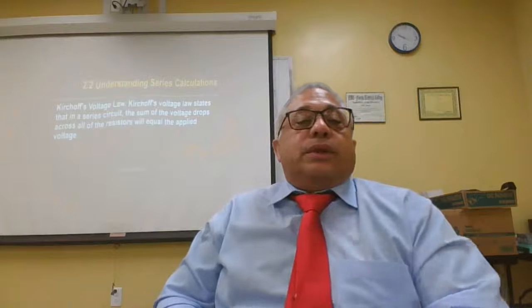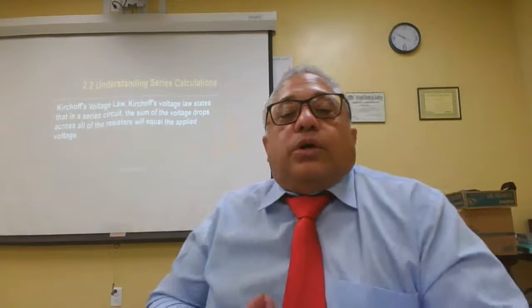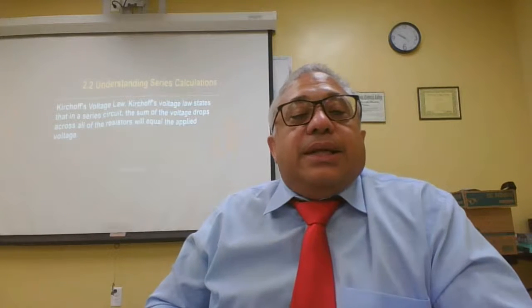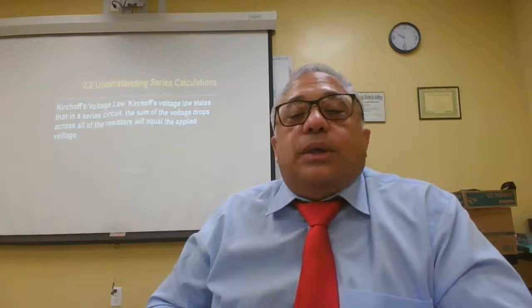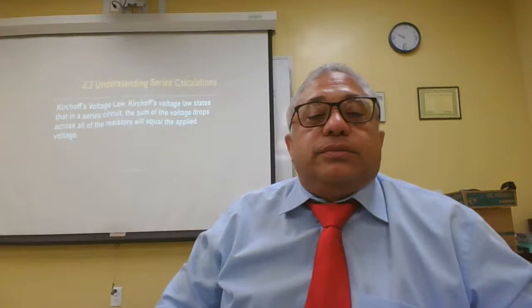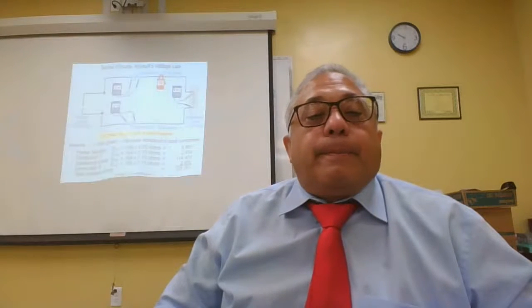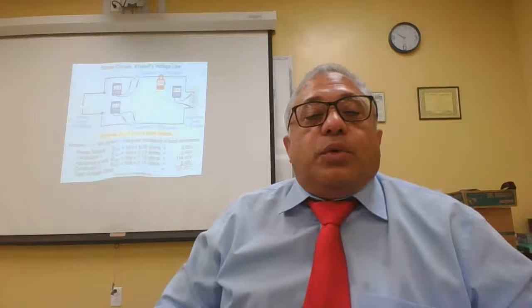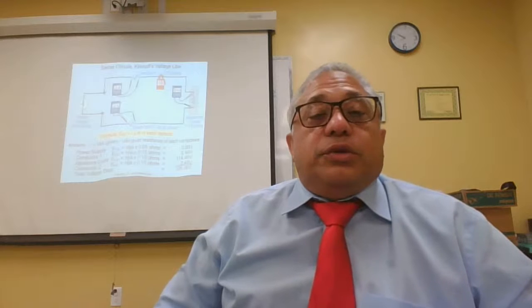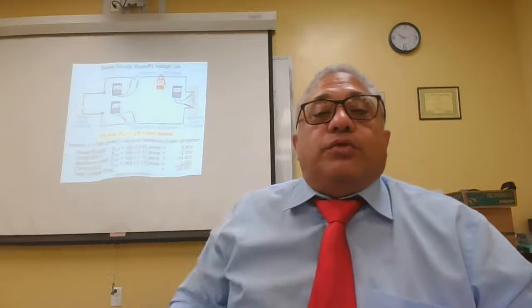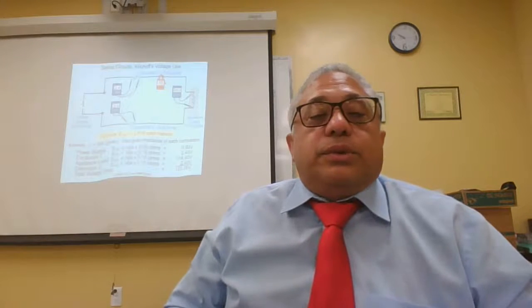Series calculations. Kirchhoff's voltage law. Kirchhoff's voltage law states that in a series circuit, the sum of voltage drops across all of the resistors will equal the applied voltage. Here we have an example where the voltage of the power source is the same as the addition of all the voltages in the circuit.